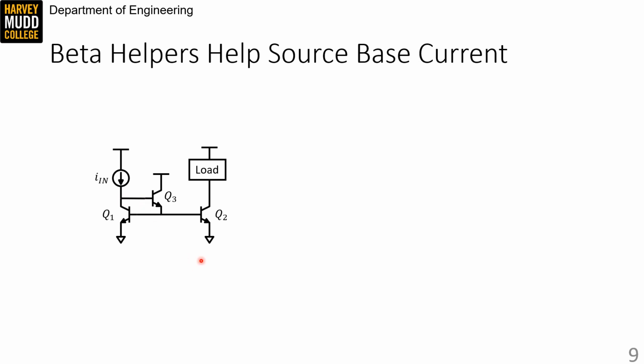That means Q1 is still kind of diode connected, just like in the simple current mirror, but the diode connection is just fancy. It's got this additional transistor in the loop in order to act like a voltage buffer. If you want to try an error calculation, you can pause the video and give this one a shot. It's optional, because I'm not holding your feet to the fire for error calculations, but this one is pretty satisfying and quick.